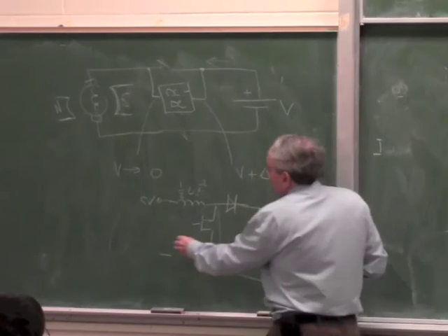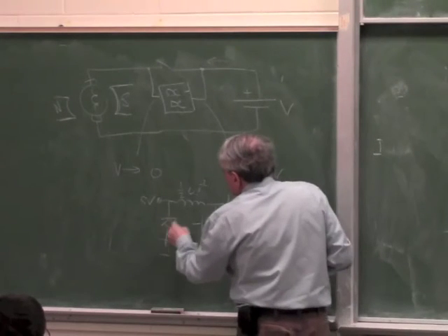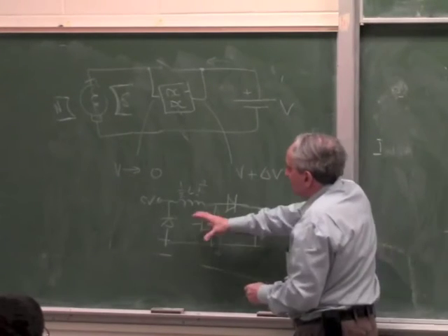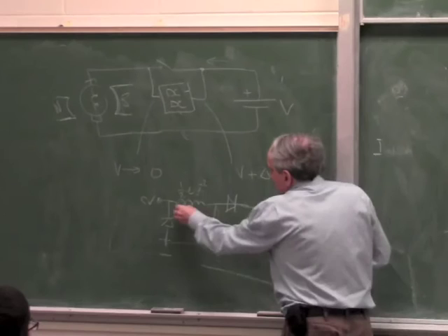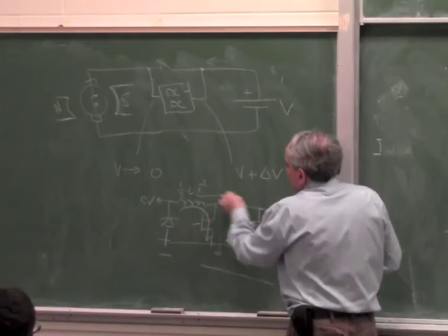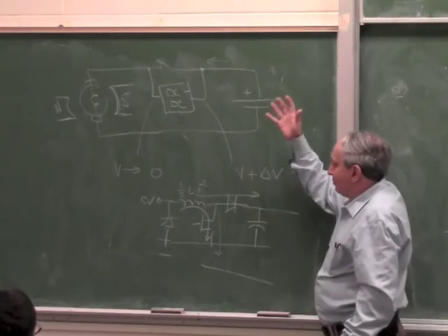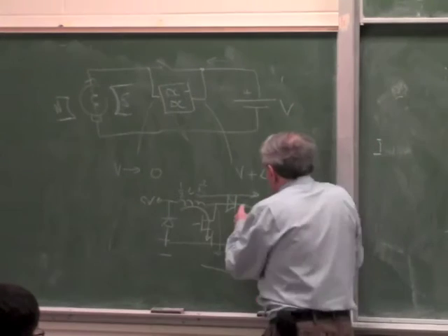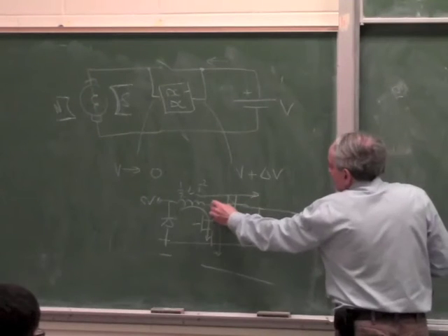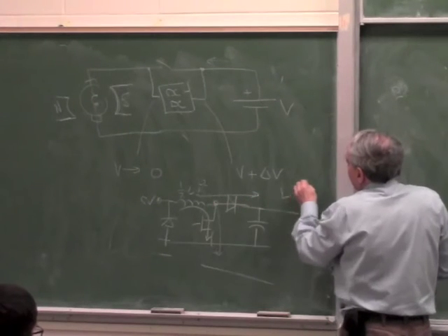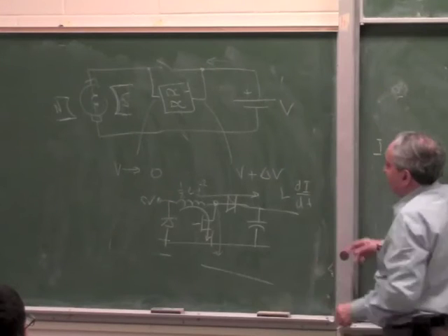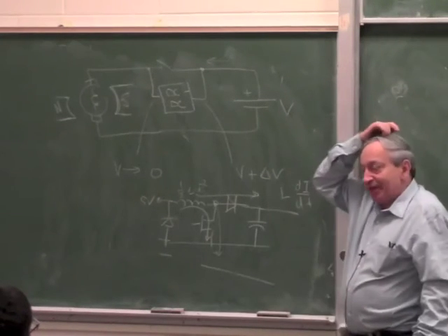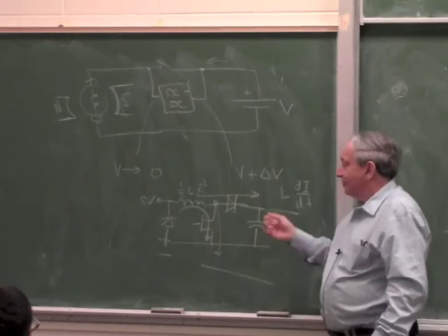Okay? And you put another diode here. The purpose of this diode is to close the loop this way. So when you close the switch, the current flows this way. When you open the switch, the current flows this way, but it wants to jump to infinity. The voltage wants to jump to infinity because, as I said so many times, the voltage here is L di/dt, and you can make di/dt as small as possible. And by playing around with this pulsing, you can correct the voltage here.